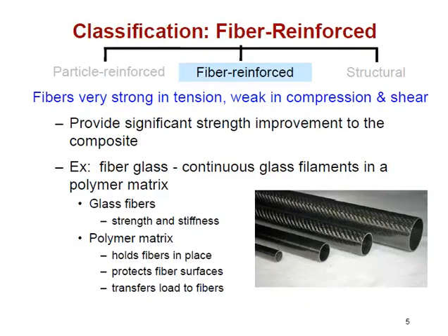Okay, fiber reinforced composites. These are probably the workhorse category for composites in general and really represent the opportunity where we can maximize on the differences in a matrix versus a reinforcer's characteristics. The thing to remember is if you are using fibers that are not randomly oriented, we're going to end up with a material that is very anisotropic. And that's because a fiber is by its very nature, if it's standing out by itself without a matrix, very, very strong in tension, but very weak in compression or shear.